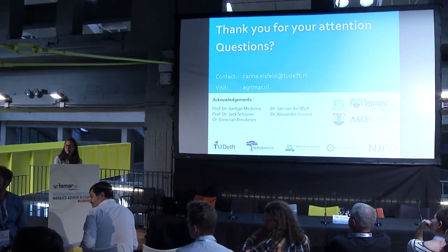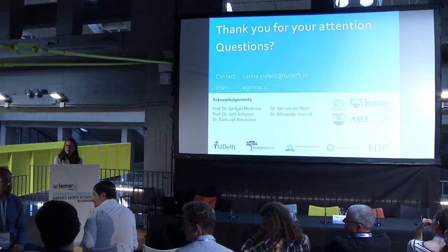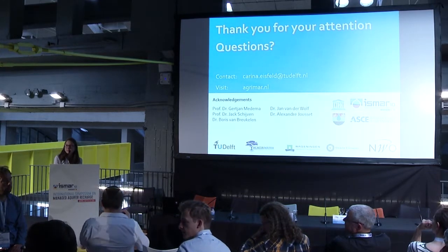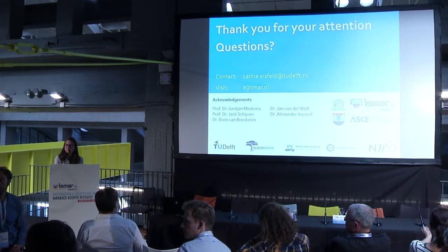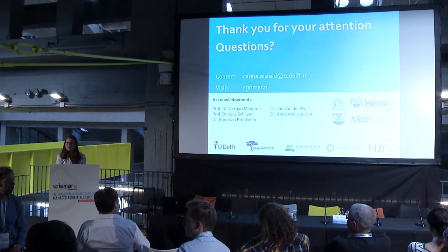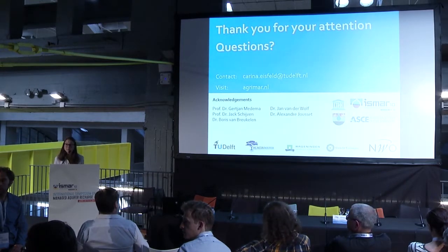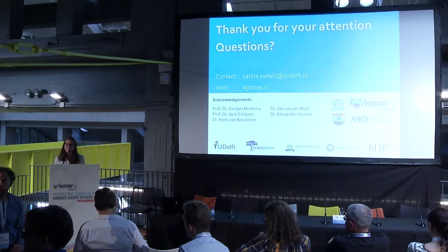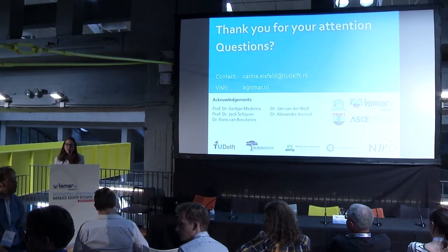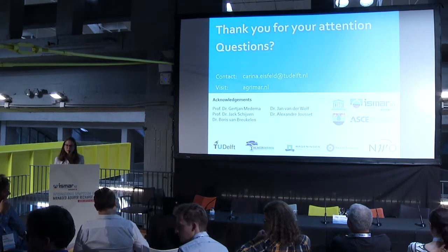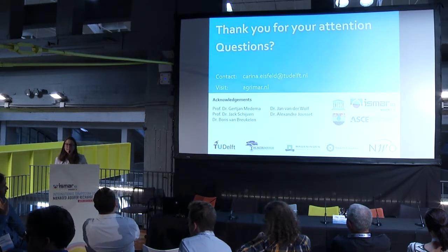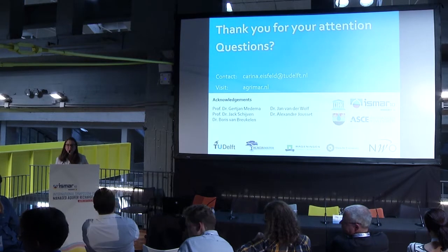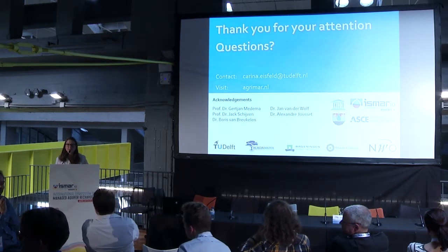My question is, you just did the experiment in the laboratory, just a column. But in fact, if you do the experiment in the field, you find something, because the drain system is very shallow, just 70 centimeters. So if the rainfall carries some fertilizers and pesticides into the drain system, then you recharge this water into the shallow groundwater. Then you put irrigation. So some contaminant pollutants will go into the shallow groundwater. So this is a key problem.